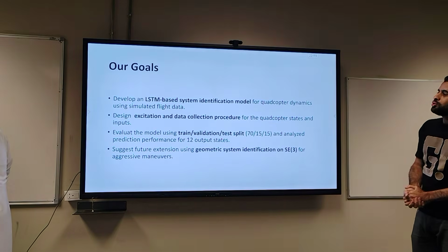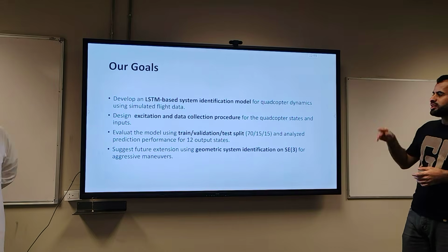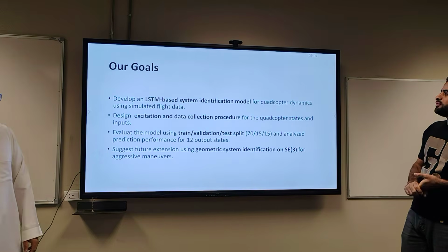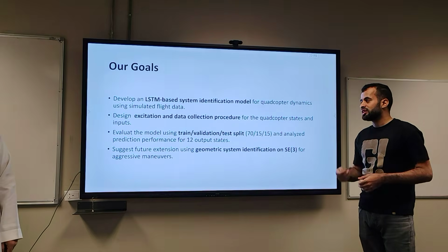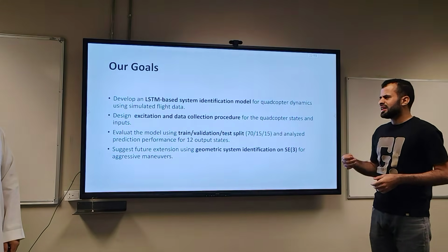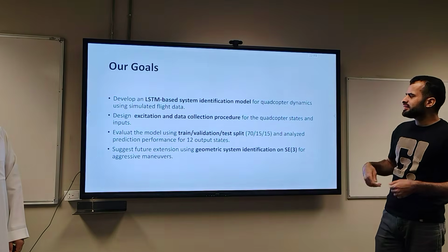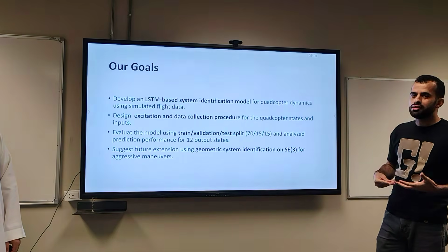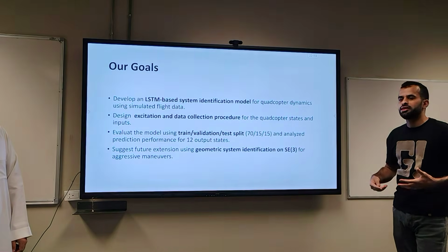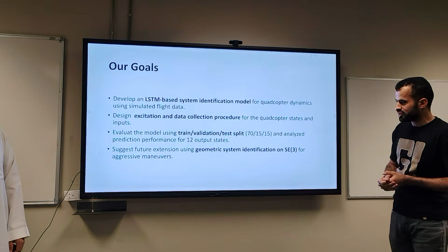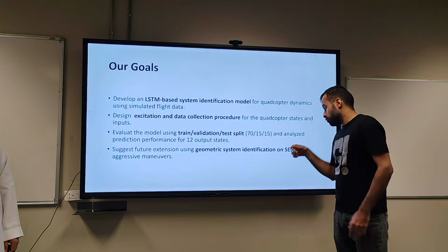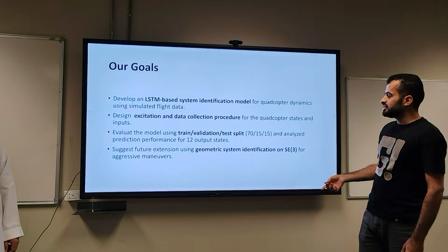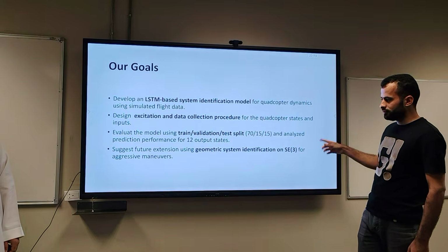So our goal is to design a long short-term memory-based system identification model for quadcopter dynamics. Then design the excitation and a data collection procedure. We need something to help us get rich information from the quadcopter's dynamics. Then training, validation, and testing the model.